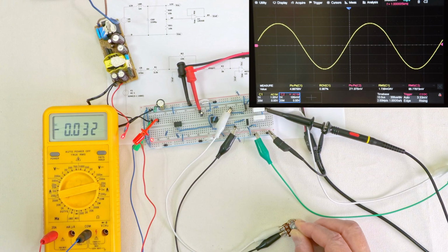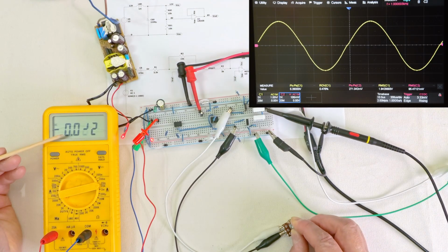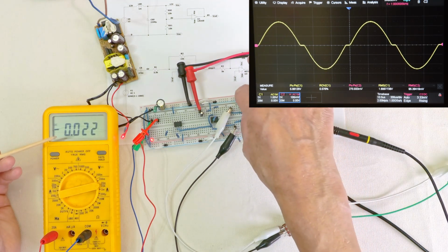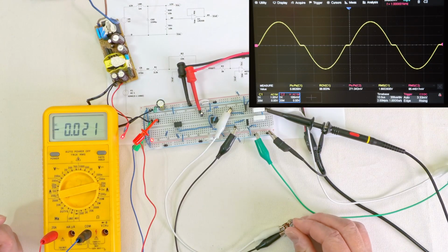But be careful, because as you can see here, the current is going up, which is quite logical as both transistors are switched on. But if I set the resistor value too high, the current will explode, as will your transistors if you're not careful, because you switch on the transistors fully, and they eventually turn into a short circuit.